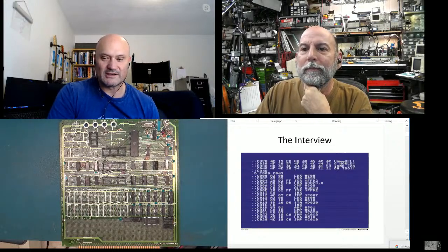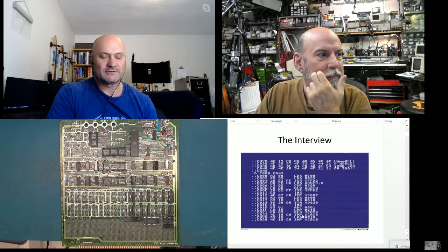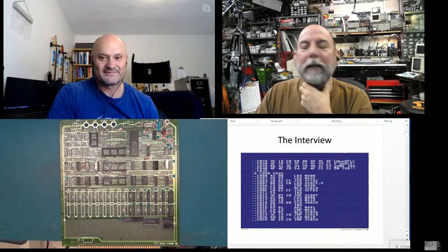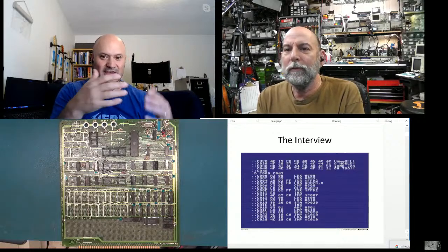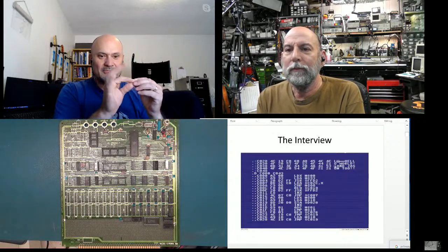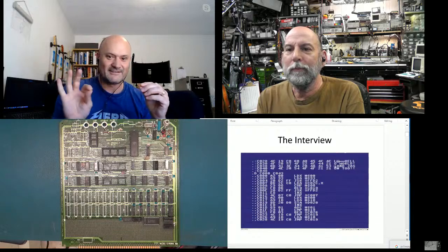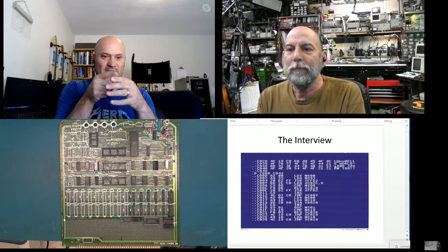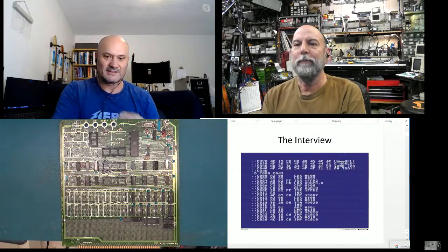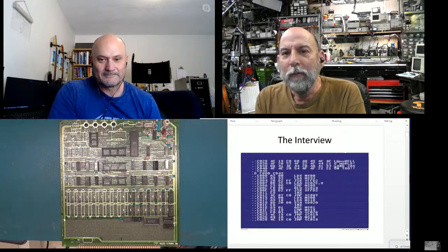Animators realized you still couldn't write to it while the DAC was reading out a line. Right, because otherwise you're changing things while it's reading it, and you get this peeling effect on your display where you see some things are moving, but some of the lines in those sprites are flickering as it goes across.